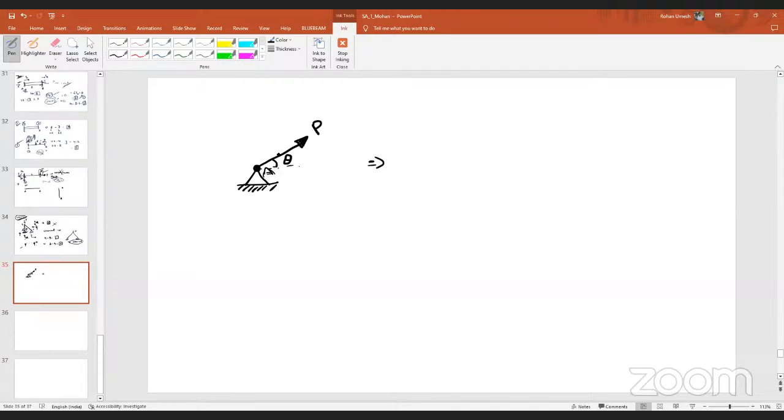First thing is that if the forces are not really acting along the horizontal or vertical direction, we will resolve them along the corresponding directions, right? So if I resolve this force along the horizontal direction, how much will I get? P cos theta, the angle with respect to horizontal, so the x component is P cos theta. The other side, it will be P sin theta, isn't it?